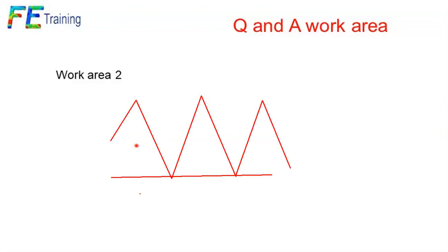There's two forms of correction factor we can use for low cycle fatigue. Both of those, one operates purely on the elastic part, one is a combined part. Again, I can't remember the names. There's Smith, Watson, and Topper, and another one. So again, in the curated solution, I'll give you the two methods we can use there.